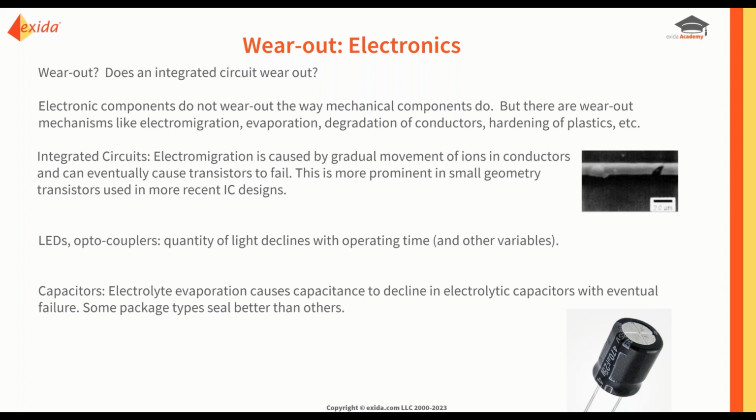LEDs and optocouplers, you've read about it before, I'll bet, but I know I have. Light declines with operating time. Now that's getting better and better. I know optocouplers used to give you charts of how rapid the degradation occurred as a function of the input current to the LED inside the optocoupler.